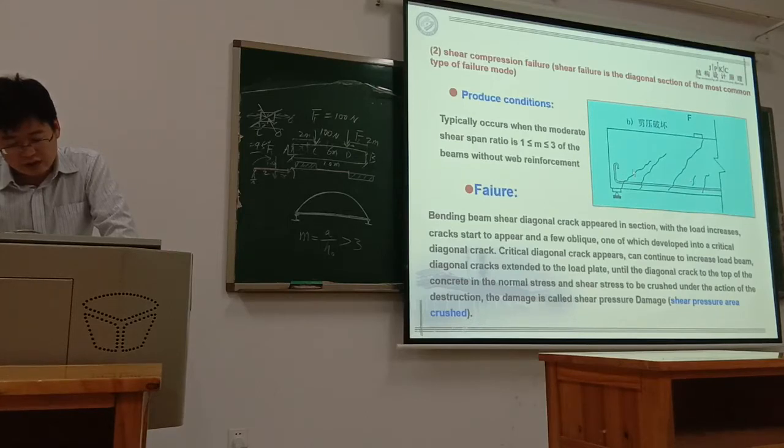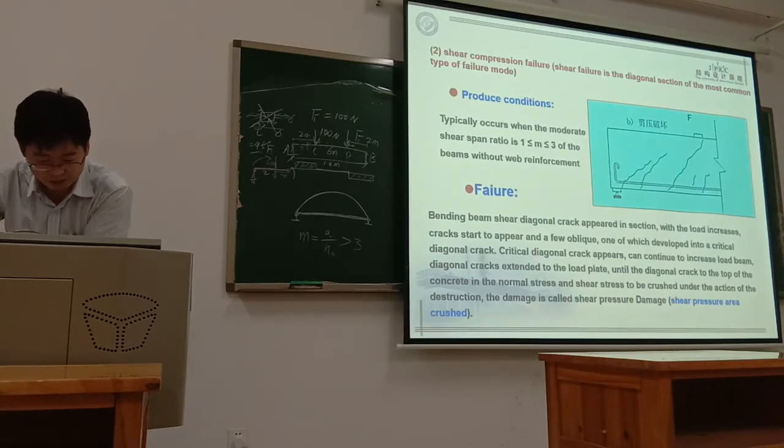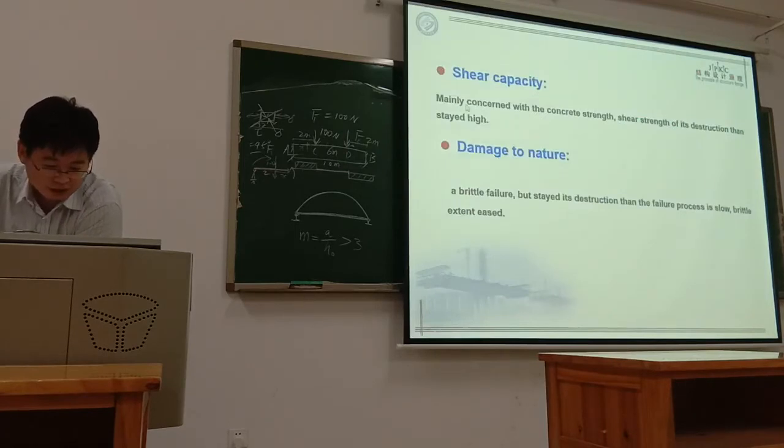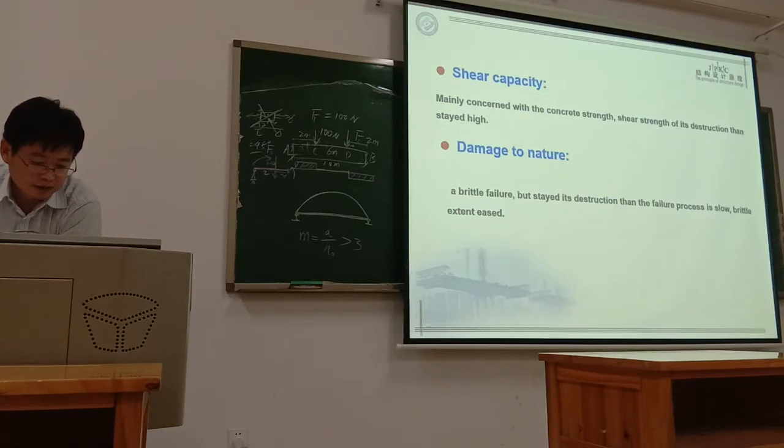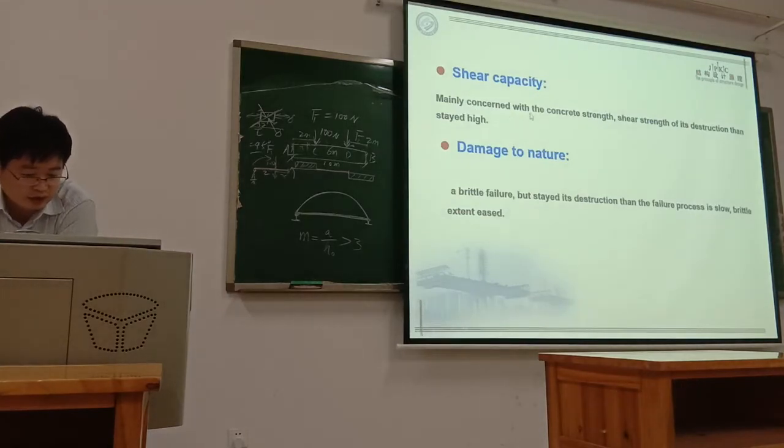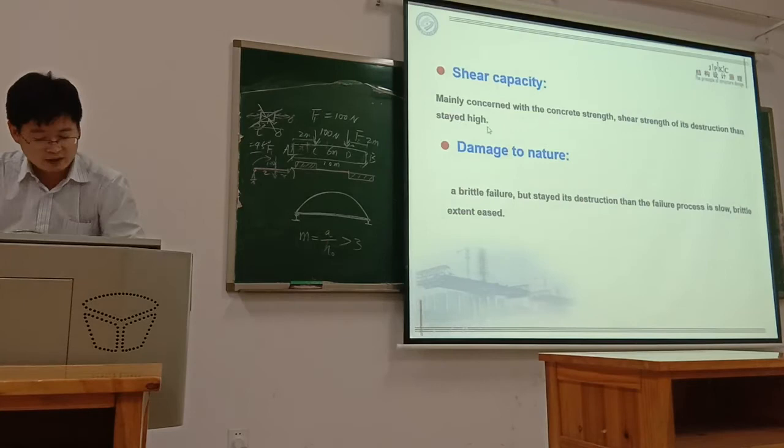So at this part, it is not only because of the tension, but also because of the compression force. So for this type of failure mode, the shear capacity is mainly concerned with the concrete strength, the shear strength, and the section height.